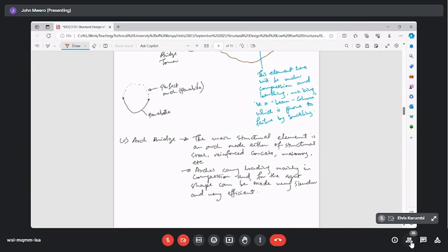So therefore, a lot of the loading will be carried by the structure in compression, but you'll have some bit of shear as well. So that's why I'm saying here for the right shape. The right shape can be made to be very, very efficient and therefore you can then do very slender structures.